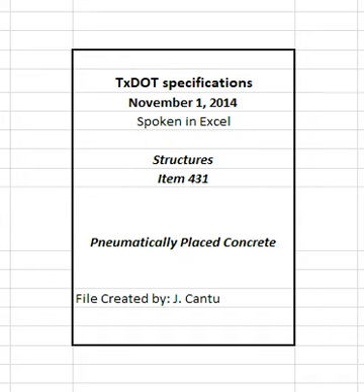Remove all deteriorated or loose material by chipping with pneumatic, electric, or hand tools when concrete is placed against concrete or rock. Cut square or slightly undercut shoulders approximately 1 inches deep along the perimeter of repair areas. Sandblast the surface to clean all rust from exposed reinforcing steel and to produce a clean rough textured surface on the concrete or rock. Wet the surface against which the concrete will be placed for at least 1 hour with potable water. Place the concrete when the surface has dried to a saturated surface dry, SSD, condition.